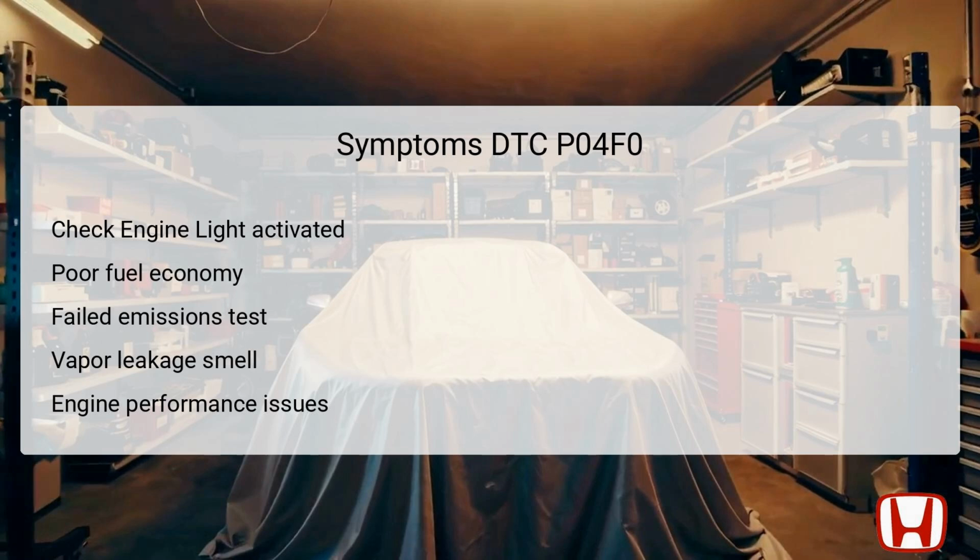Drivers might also encounter a noticeable gasoline vapor smell, particularly near the fuel tank area, suggesting a leakage issue within the EVAP system. As a result of these issues, engine performance may stutter or lag under certain conditions, making it imperative to address the DTC promptly.